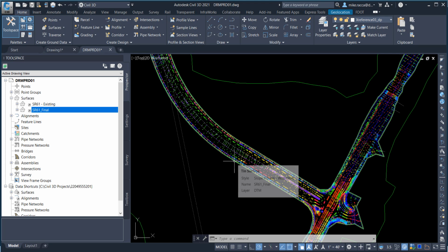Exercise 4.4, using the Xlist command. The next steps will show you how to use the Xlist command. The Xlist command allows you to list objects that are in an Xref file such as layers, colors, line types, etc. On the command line, type Xlist.